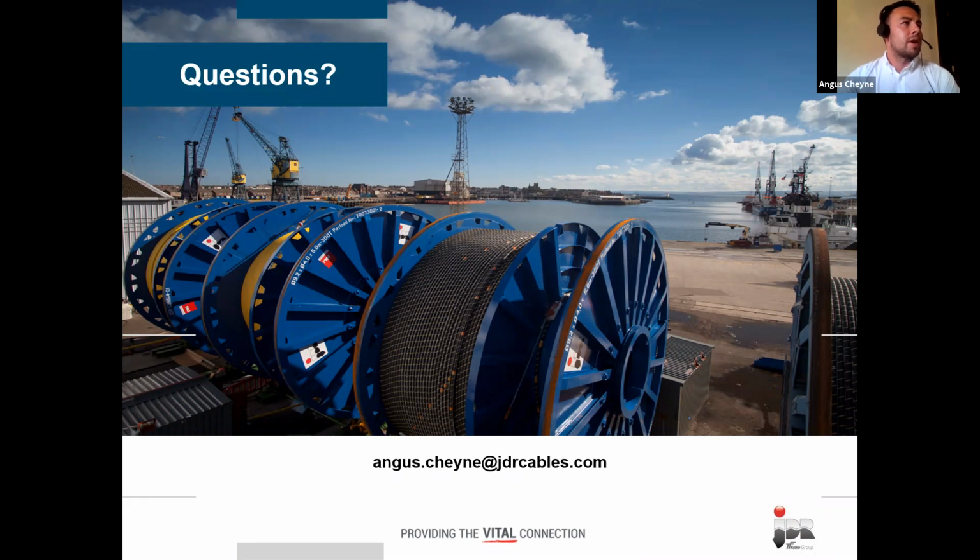What is the required qualification testing or inspection required to reuse a subsea bundle after project lifetime, say 20 to 25 years? So after that sort of design life, that would be probably around the top level of design life. It's the typical design life that we would supply umbilicals to. So it's certainly not the maximum, but it's what we would generally supply them to. So at that sort of period, it is probably becoming a consideration as to whether it is still fit for purpose.